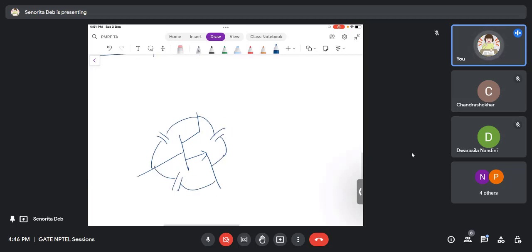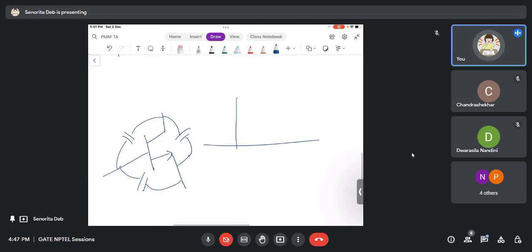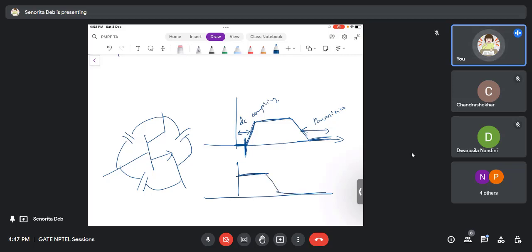Therefore when we draw the amplifier profile of a BJT, we draw it like this and we say this is the low frequency caps doing. Because of the low frequency caps we get 0 here, and here because of the high frequency parasitic caps we get 0, and this is because of the DC coupling caps we get 0, and in between we get the output. But if you do it in an oscilloscope, you will see this value is so small that it can be approximated as a low pass filter action only. Is the doubt clear, Chandrasekhar?